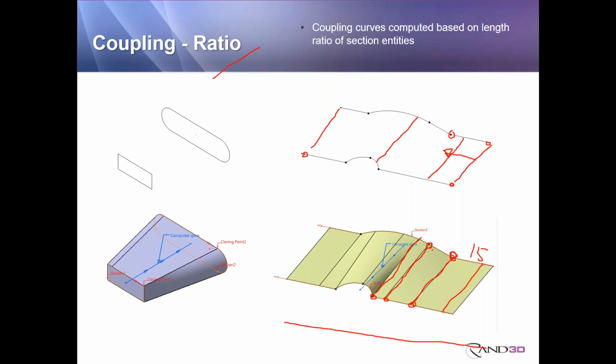Now, over here in this one on the right, same thing's happening. This closing point again is getting connected to the closing point. And then it just starts to work its way around proportionally. When it gets to the end of this particular item here, whatever that distance is around on the oval, it finds the corresponding percent point over here on the rectangle section. But you'll notice here, it doesn't connect right to the corner. Part of this arc here is actually getting blended to part of the straight piece over here.